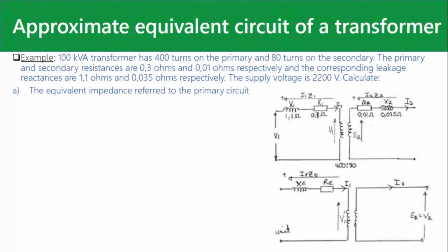So, all right, you see 100 kVA transformer. Transformers are always rated in kVA, never in kilowatts, always in kVA. Let's just make certain we know what we're talking about there. There's your power triangle. This is S, apparent power in VA. This is P, true power in watts.